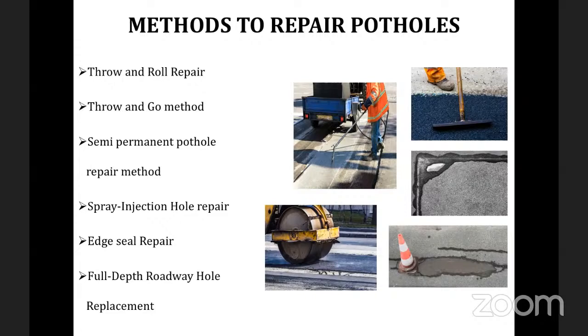Then the material will be compacted using the roller or the truck tires to allow for a tighter patch. And the maintenance crew will move to the next potholes, and the same procedure continues. So here, the potholes will be cleaned, and then the material we have, maybe the ready-made or the cold mix, will be placed, and then it will be rolled. So that's the throw and roll method.